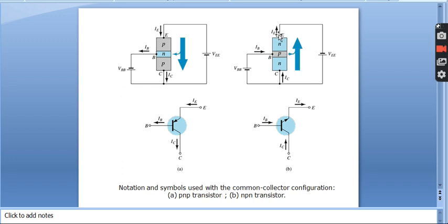That means in case of NPN transistor, the emitter current is out from the transistor, that means out of direction. So that's why I show the outward direction to the collector, which forms a closed path. Again the base current will be into the transistor. These are the circuit configurations, that is how to make connections in common base configuration along with their structure and their symbols.